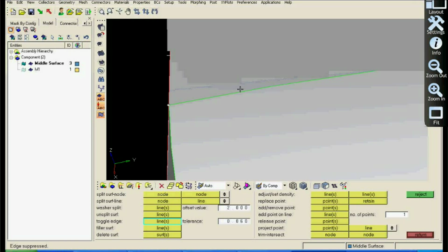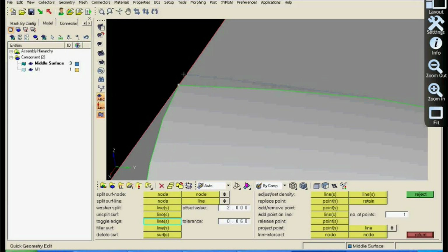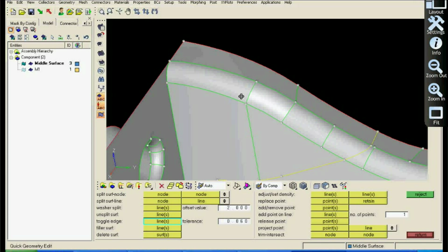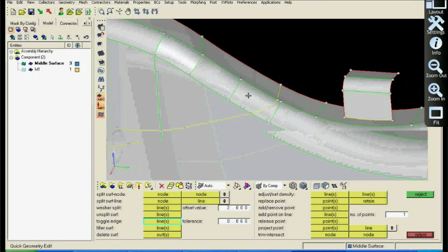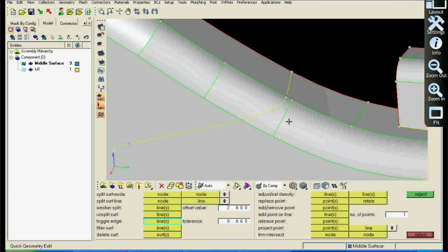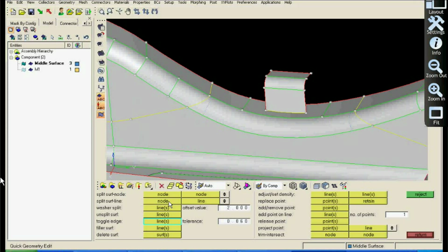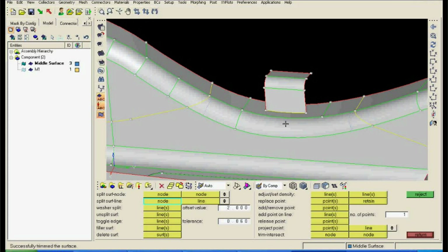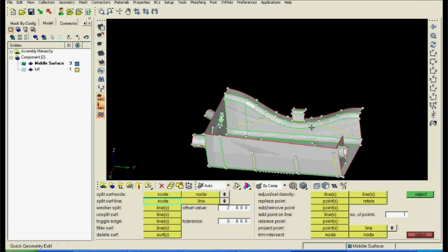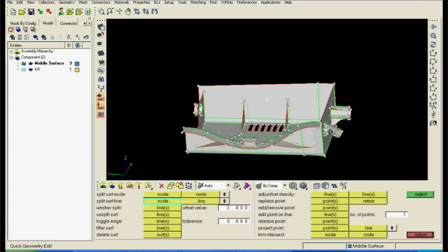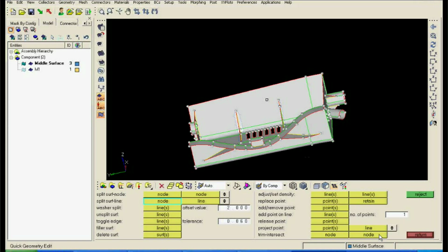That was the intention, and that will solve the problem in some way. I will also toggle this line here, and this line here, again creating node to line. This is kind of repeating work I had to do, because I removed those surfaces earlier by mistake. Alright, so again, ready for the mesh, we go for auto mesh,